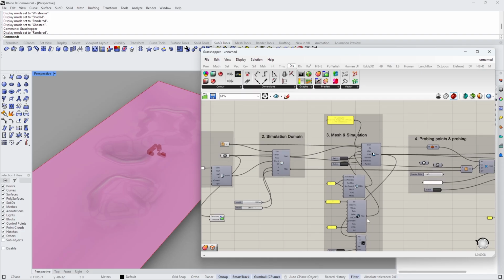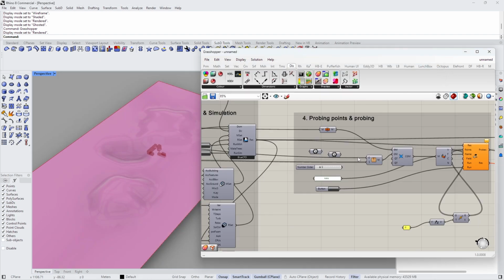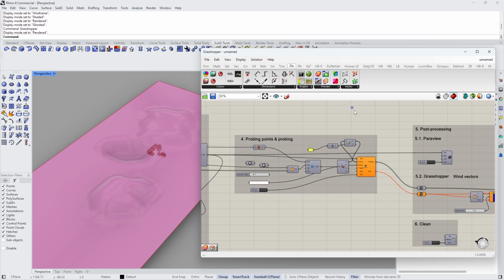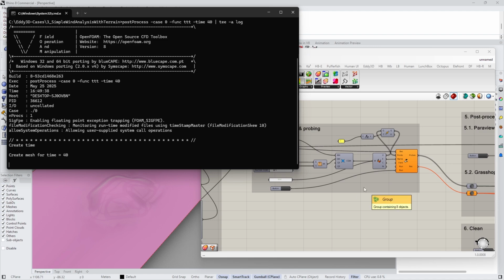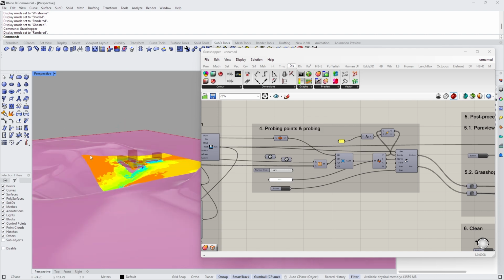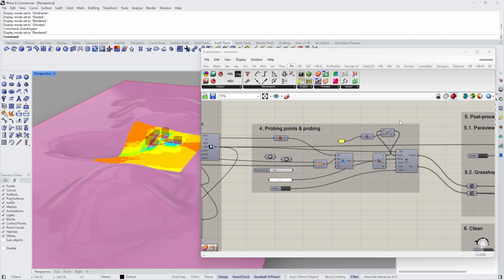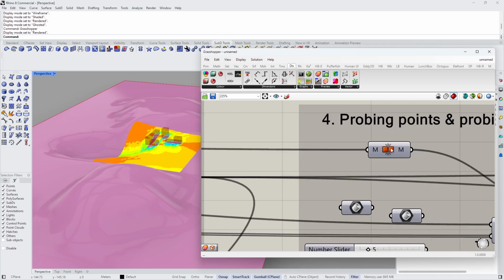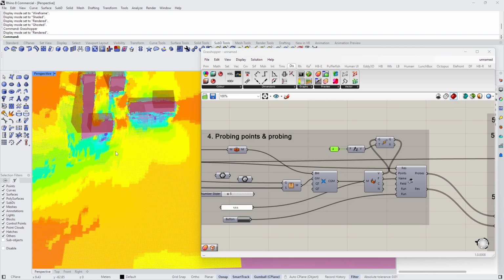All right, that ran. Again, we can have a look at this. It doesn't tell you much yet, but what's way more interesting is the probes. I'm not sure why they did this. That seems a bit off. We can go through this in more detail. But what's cool is that here the arrows, basically the probes, were placed onto the surface and then offset. The probe points were projected onto the terrain and then offset by 2 meters, so they are hovering above.